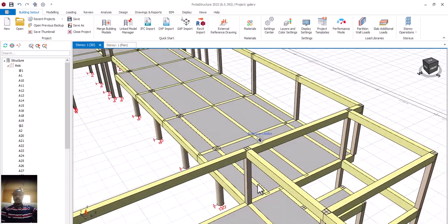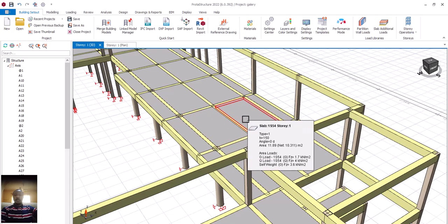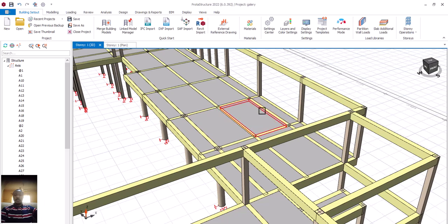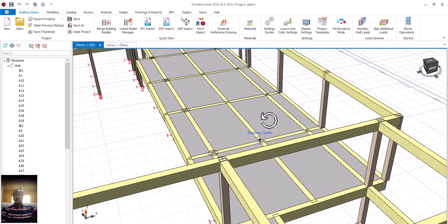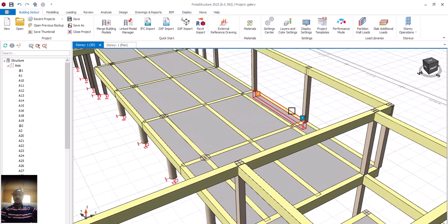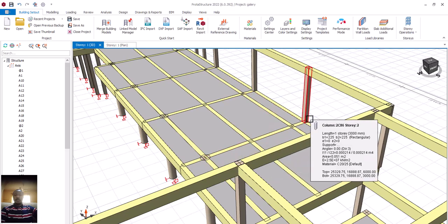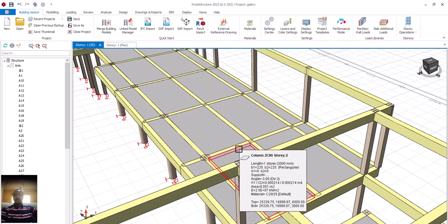What we are trying to do here, based on the architectural drawing, is that this point is normal, and the step is 250. Is that okay? 250 and 150. Now where do we have 250 and where do we have 150? I'm going to explain it all. So let's start. Looking at this place, this place is normal in height. This is a normal step, and what the architect wants is not a situation whereby you're already seeing a slant beam. You want the beam to be normal at the outside, while when you enter inside you now see the slant beams. Is that okay? And the slant gallery.